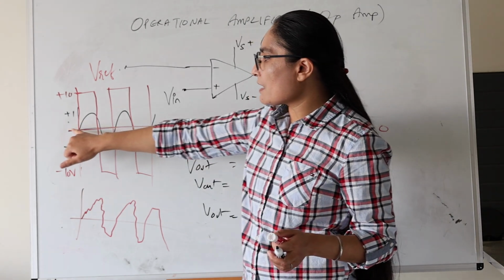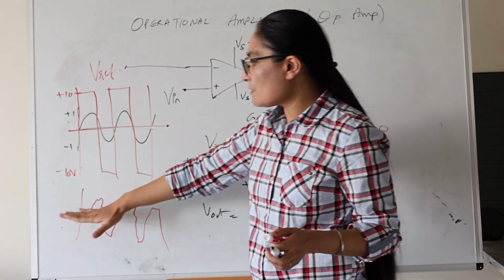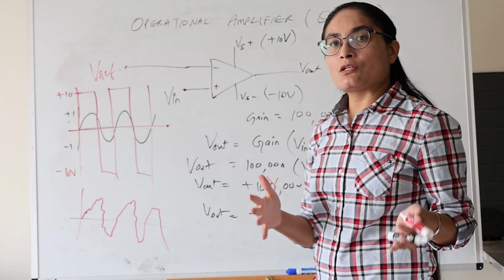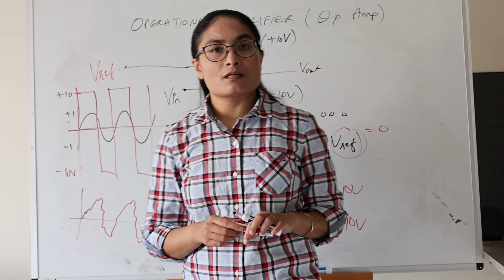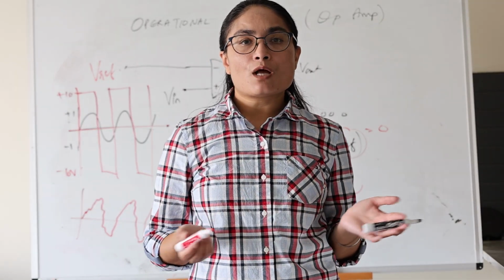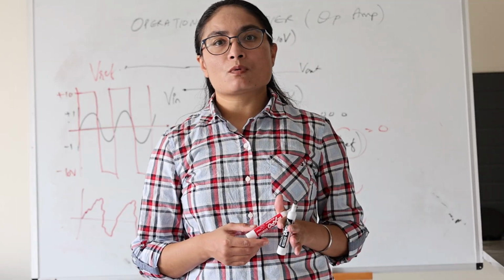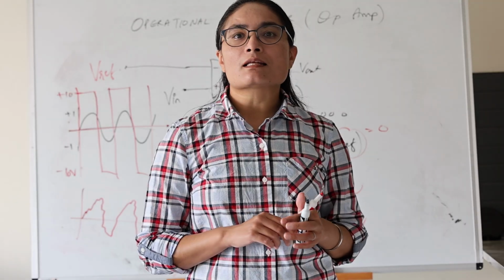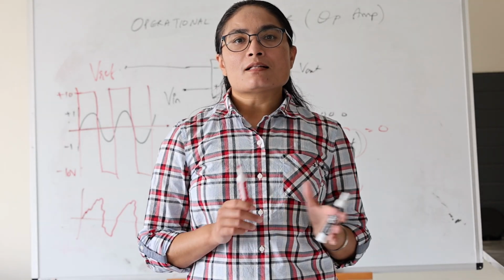So rather than defining just one threshold, we define two thresholds with some hysteresis, and we can use what we call a Schmitt trigger circuit. I'm not going to cover that in this lecture today, but if you want me to expand upon what a Schmitt trigger circuit is, let me know in the comments below and we can cover that in a separate lecture. I'll stop here.